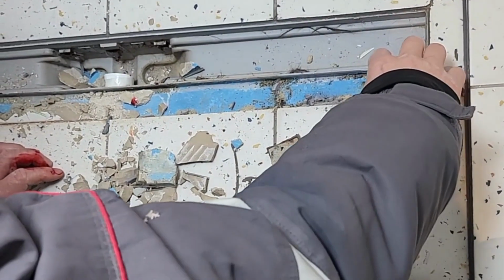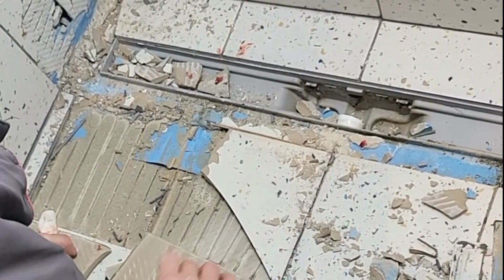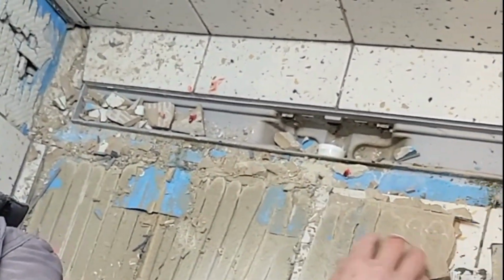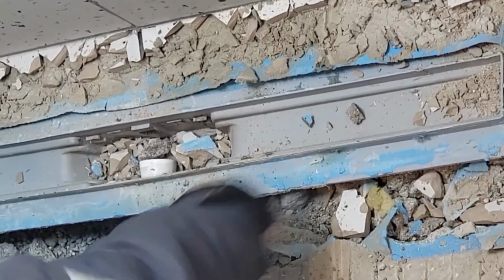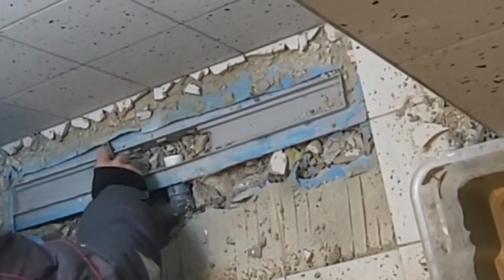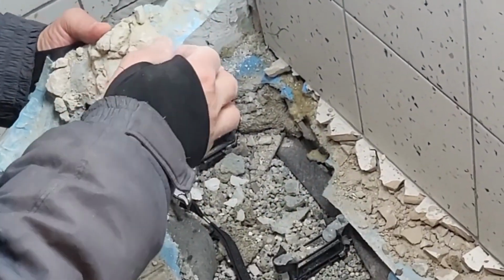After uncovering the assembly, we determined two things. First, there was no butyl tape at all. Second, the reinforcement fabric covers only a part of the gutter flanges. This means that the waterproofing was not reliably and tightly connected to the plastic gutter. Through this connection, water could have entered directly into the floor structure. It was this specific error that was identified during the investigation as the primary cause of the leakage.